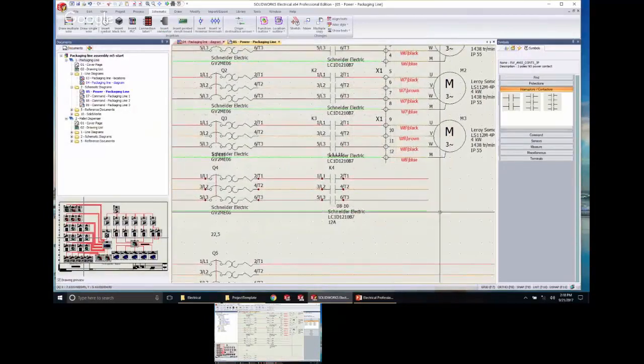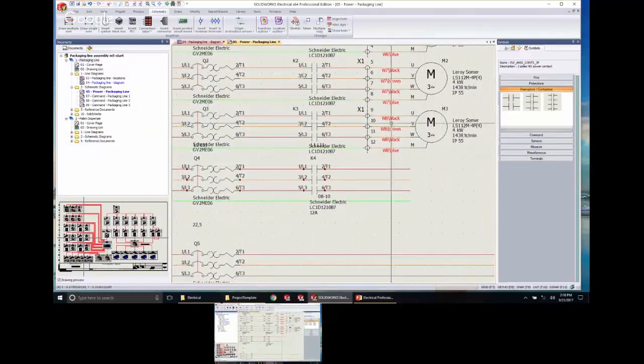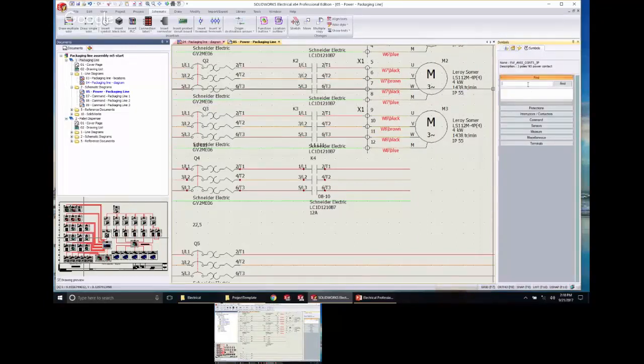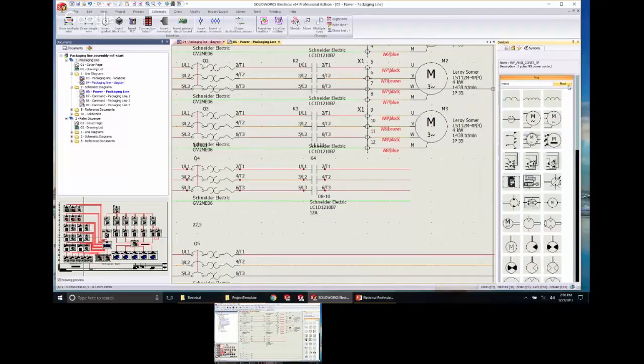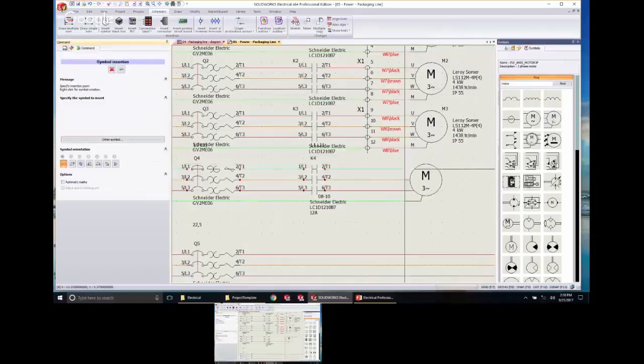And then I'm going to put in the motor symbol. Okay, and in this case, I'm going to use another tool. So up here at the very top, we have a find. If you don't know what the symbol is called, or you're not sure, I can type in motor and hit find. And every symbol in my SQL database associated somehow with a motor shows up here. And then I see, oh yeah, this is the symbol I want. That's the ticket. So again, I'll put that in here. Place it down.